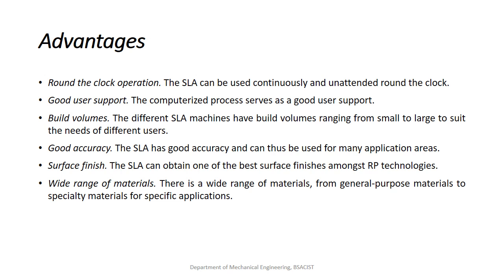The surface finish obtained is one of the best because the laser scanning is very thin. Small little layers solidify, creating a better surface finish. A wide range of materials, from general purpose to specific applications, can be manufactured using stereolithography.